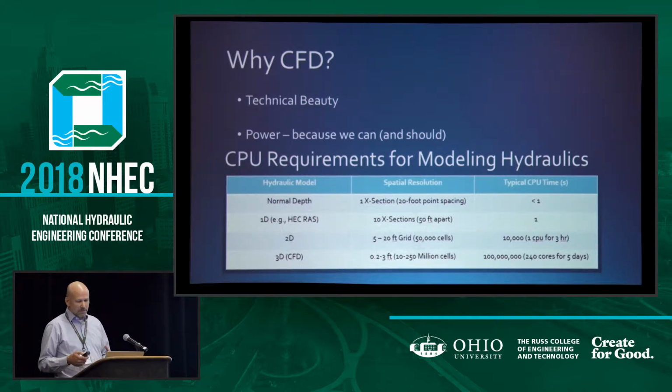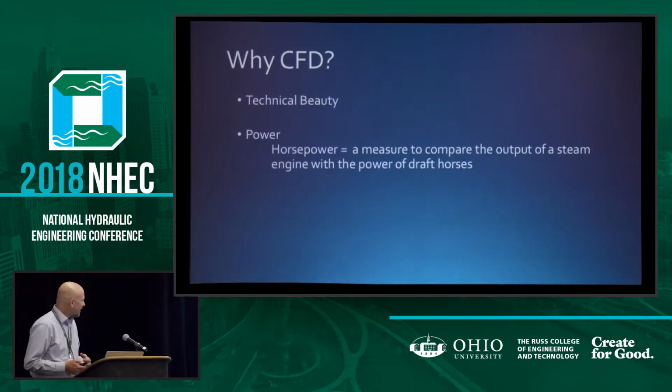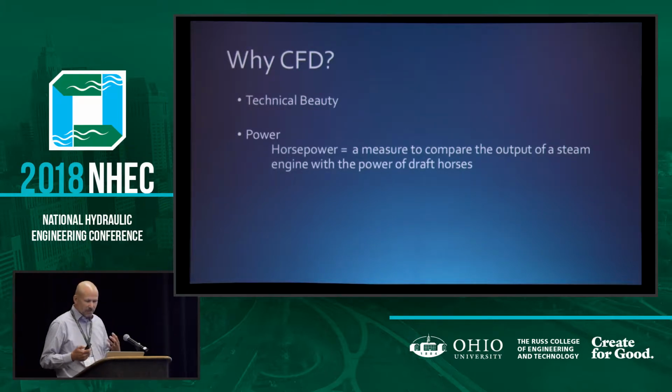3D, you've got to run on multiple cores, maybe 200 cores sometimes, and you've got to run it for days. That's about 10,000 times more effort than the 2D model, or 100 million times more than a 1D model. Again, don't hold me to those numbers, but that gives you a feeling of the range of power in CFD.